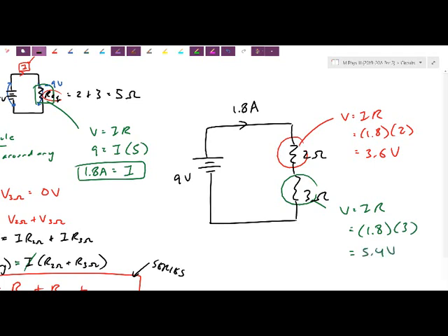Let's see if Kirchhoff's loop rule is actually applied in my real circuit. I had gained 9 going through the battery. I'm going to minus 3.6 because that's used up for my light bulb, minus 5.4. And if you add up 3.6 and 5.4, no surprise there, this is giving you 9. So I pick up 9. Over the course of the 2 resistors, I lose my 9 volts so that I'm back down at the bottom of the slide. I'm ready to take the staircase up again.